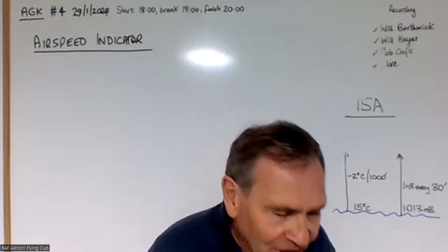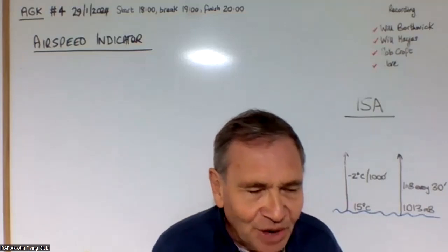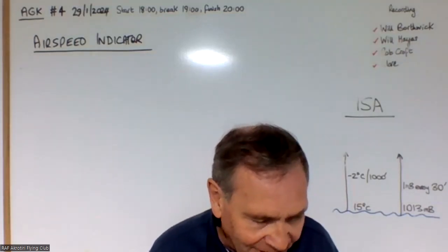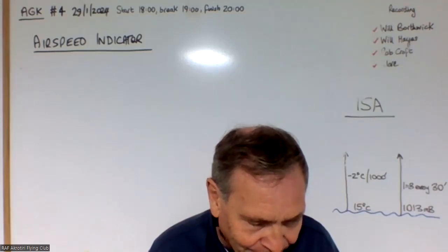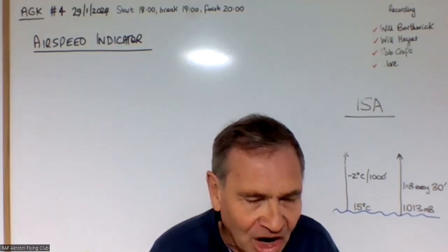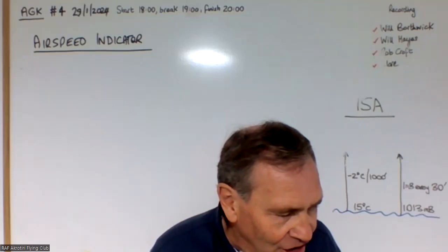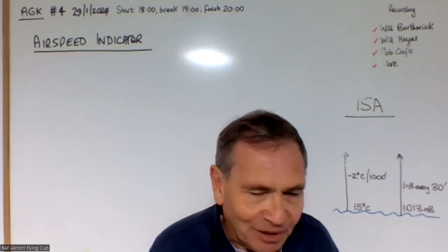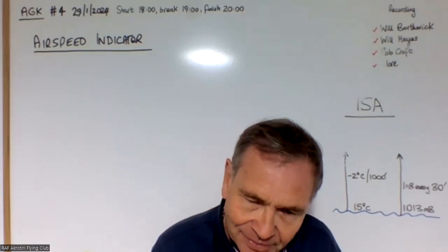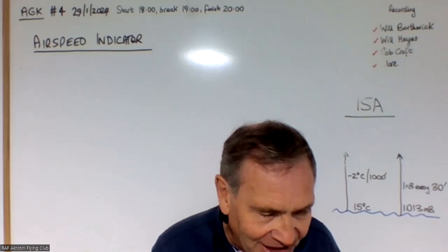Yes, although the pitot tube would still have in it the static pressure from like before, wouldn't it? Yeah, so it would have whatever pressure was in there before it got blocked, I guess. That's right. That's exactly right. So what would actually the needle be showing you? The pressure it was at the time, so it would be a false reading.